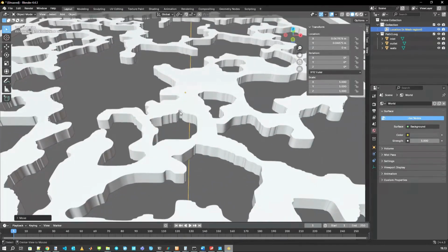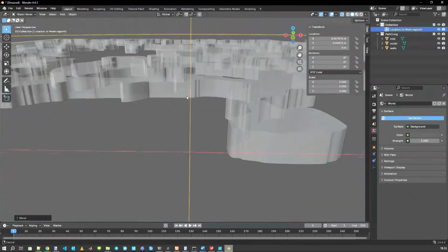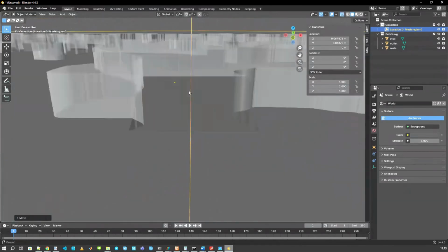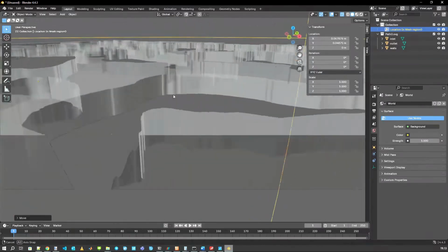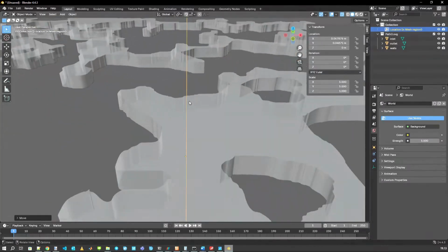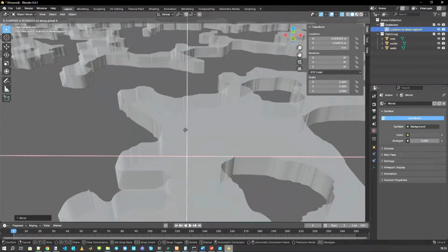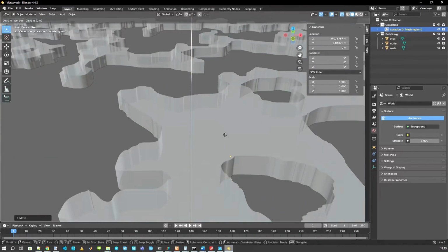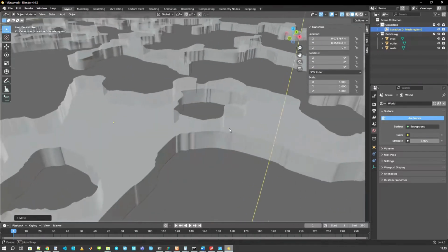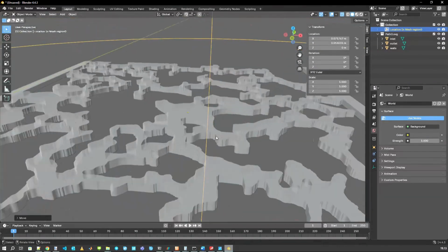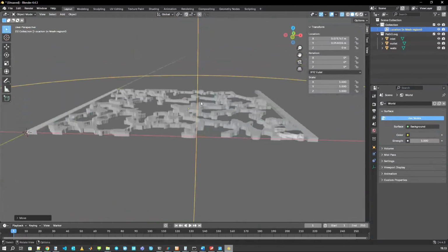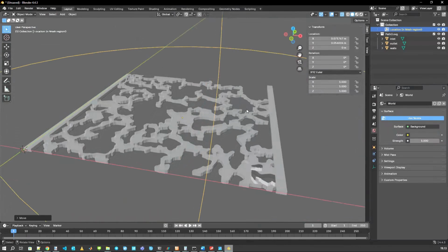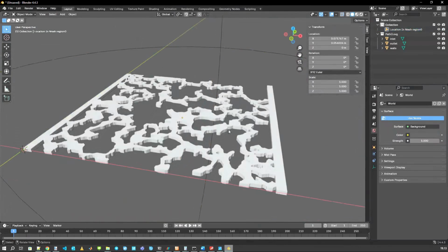By pressing Alt and Z, you can turn on the X-ray mode, which allows you to look into the mesh. As you can see, it is inside, so I just want to move it a bit in the X direction and then a bit in the Y direction to make sure it's in a good place, and snappyHexMesh can see it. So far, so good.